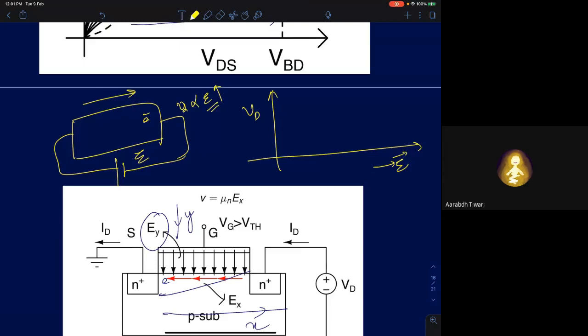But understand, this is a semiconductor lattice where the electrons are traversing, so these electrons are undergoing constant collisions with the lattice. After a point, if you keep increasing the electric field, any excess energy the electric field imparts to the electron will be absorbed by the lattice.